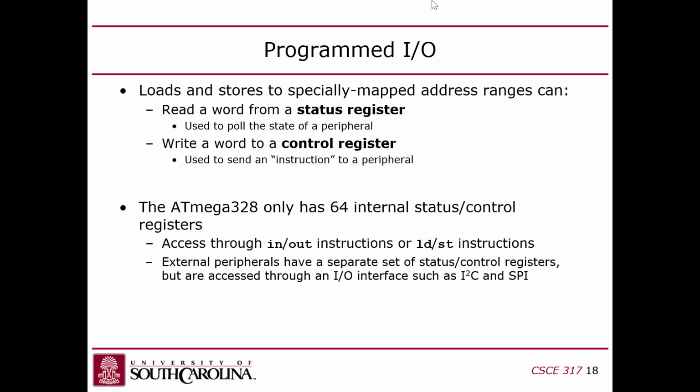Interrupts are ways for an I/O device to get the attention of a processor, to interrupt whatever it's doing, and to force it to go to a specific address in the code called an interrupt handler, which forces the processor to then go through programmed I/O and query and figure out what's going on and what it needs to do to respond to that interrupt.